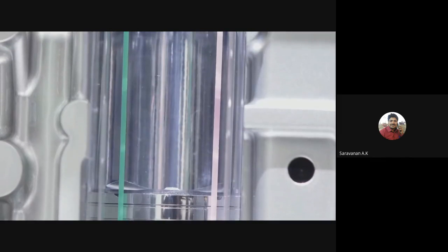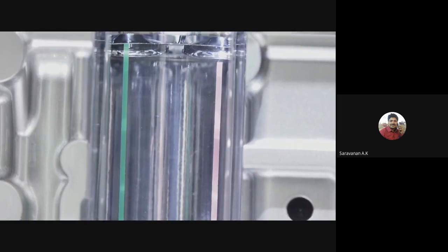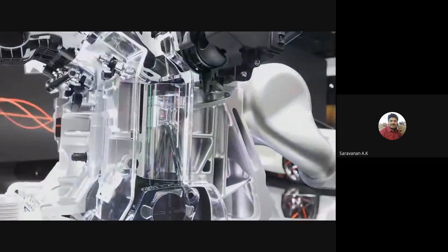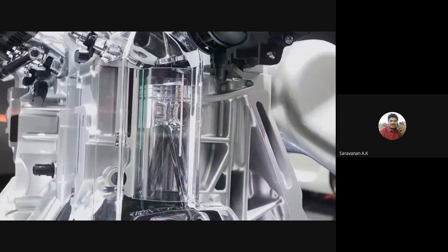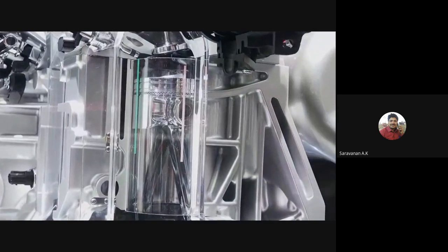This so-called mirror coating is the result of the same plasma sprayed cylinder liner that's used on the Nissan GTR. After the plasma spray is applied, there's a very fine cylinder bore honing, which ultimately leaves behind a very strong, durable, and highly reflective cylinder liner.